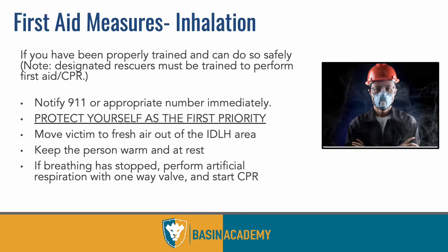So if someone gets exposed through inhalation, then we have to assess what the priorities are. And the first thing you want to do is protect yourself, right? You want to call 911. If you have two people there, the other person should call 911. If you're the only person there with the person that needs to get rescued, that needs to be your first call before you go help them. You want to protect yourself, meaning you have to have the right respirator on, the right rescue equipment on. You need to be able to rescue them effectively, because if you go down while rescuing them, that creates two people that need to be rescued in the future instead of just the one.